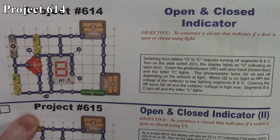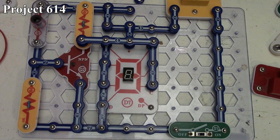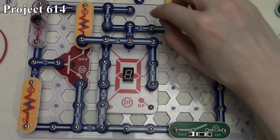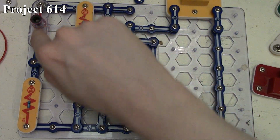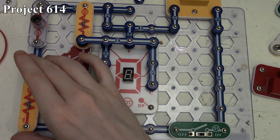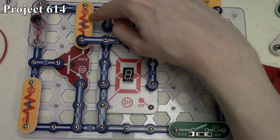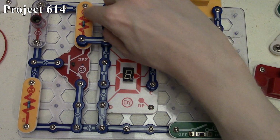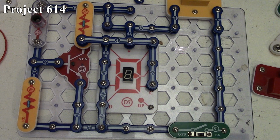And here's project 614, the open and closed indicator. There it is in the book, and here it is on the board. So we have 6 volts, and we have our slide switch turning the entire circuit on and off. That is feeding our photoresistor, which is then controlling the base of our NPN transistor here, along with our 10,000 ohm resistor, dropping it across here. And we also have our R5 100,000 ohm resistor going into our NPN transistor there to control it.